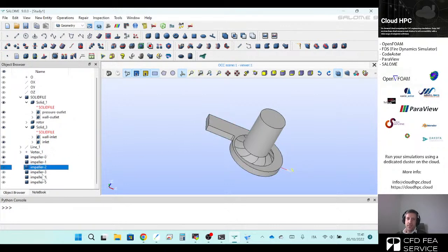We actually have several of them, and we are just replacing this central impeller in the meshing, which is going to be made with Snappy. Okay, so we just replace these 6 impellers in order to generate several meshes in order to compute our simulations in different geometry conditions.